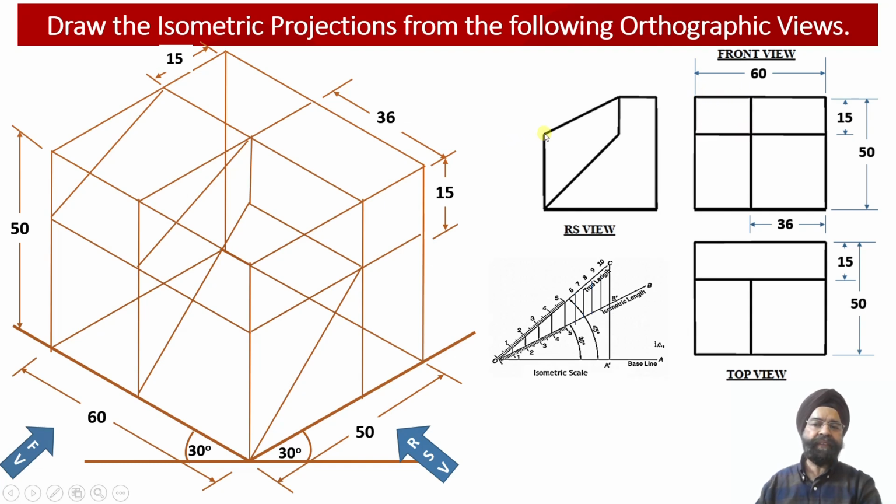And then we can check the lower portion of this web happens to be vertical into the side view projections over here. So now we can have this rectangular surface which is going to measure 24 millimeter length and 35 millimeter height of this rectangular cross section over here. So this rectangular cross section true shape is available with us into the front view projections over here, and this vertical edge means that there is no change in cross section at the front face over here.